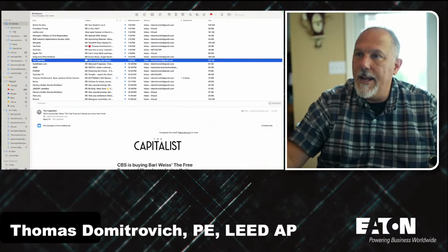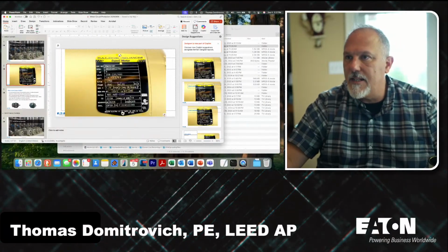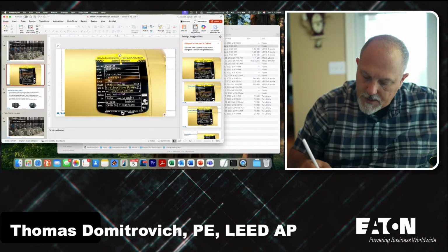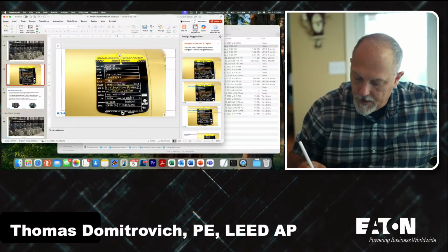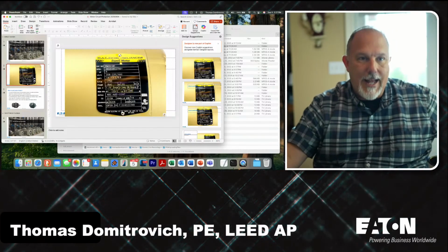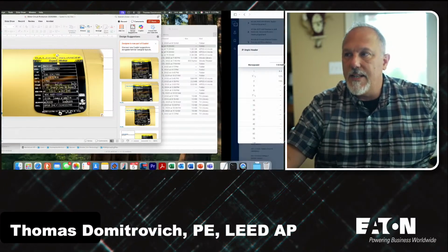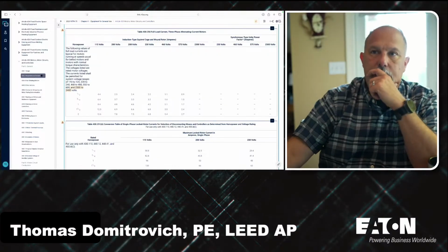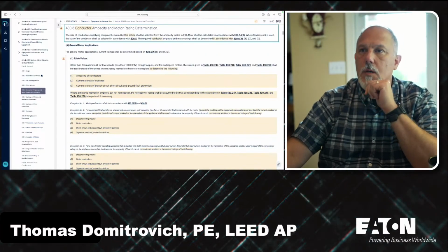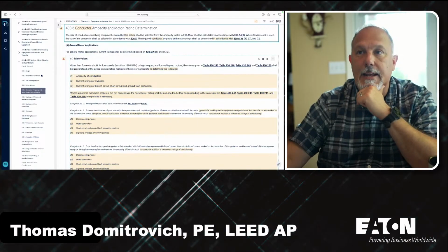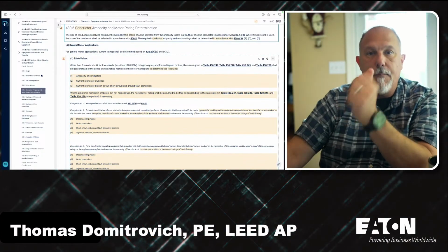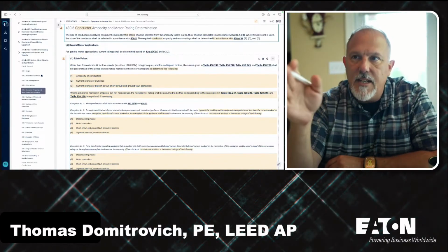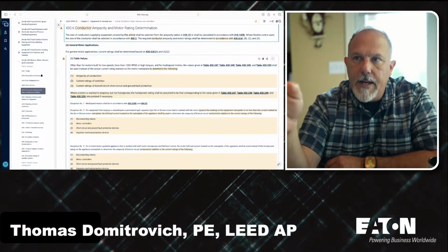The nameplate says full load current is 14. So this has 14.0 full load amps at that voltage. Make sense? Beautiful. All right, so I'm going to go back to where I once belonged. Okay, so 430.6(a) tells me I'm going to use the tables for the ampacity. So I'm going to use this 16.7 amps for the ampacity of the conductor, the current ratings of the switches,